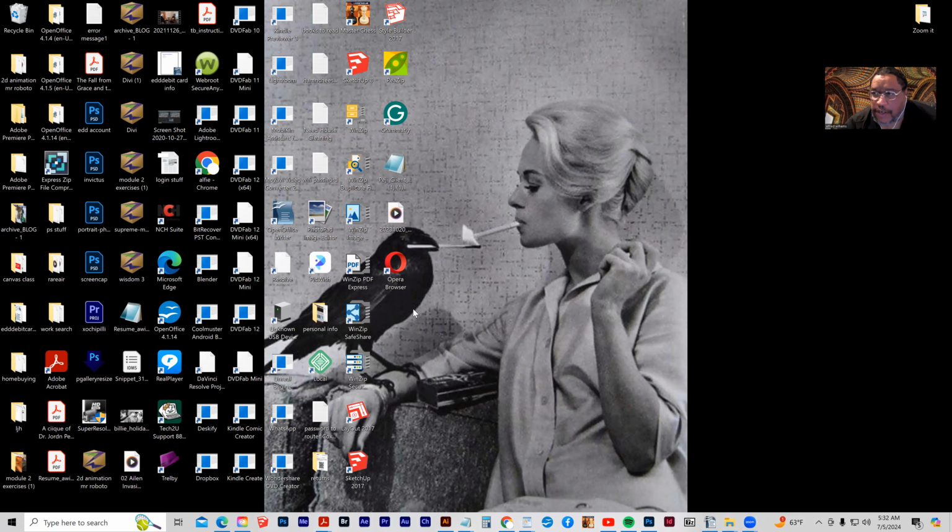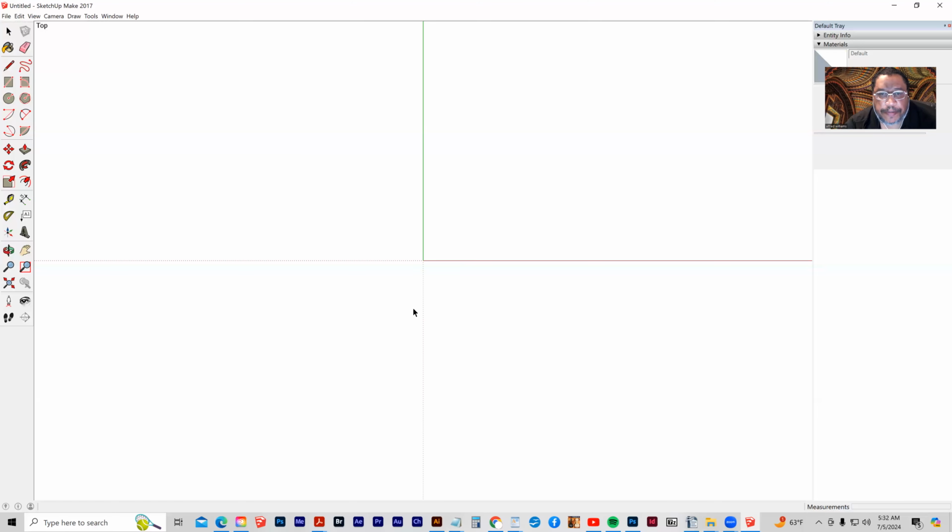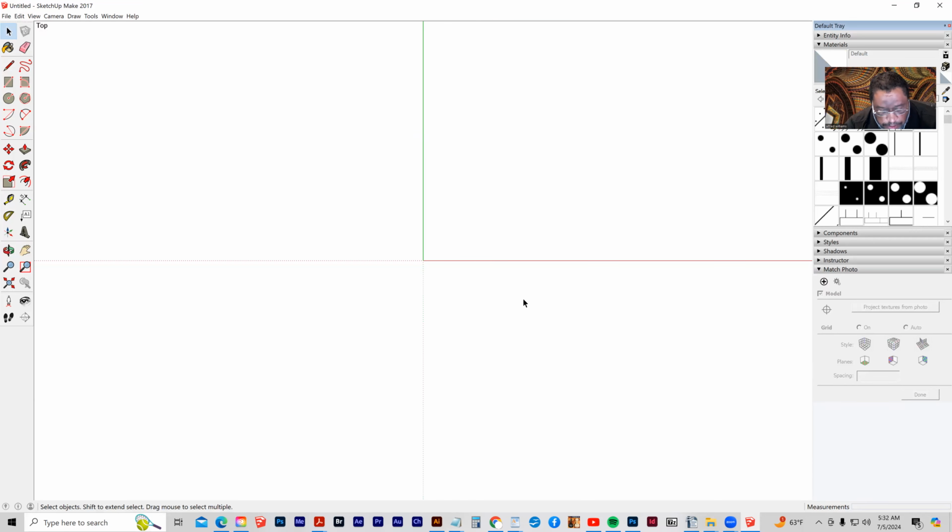Let it launch. Okay. And the first thing I'm going to do is draw a house with a 30-foot by 20-foot dimension. So I'm going to grab my rectangle tool, click from the center, drag outwards, type in 30 apostrophe, comma, 20 apostrophe, enter.